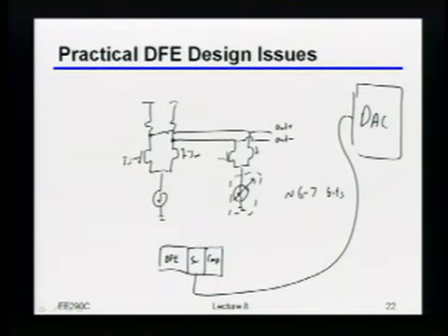Again, it's not that fundamentally the DAC has to be off on the side over there. It's just that, let's say I have another DFE nearby that I want to do. If I shove the DAC right next to the DFE itself, it'll eat into your pitch. It'll force everything to be spread apart, and then you'll be paying for really big wires in the front over there. So this kind of design, even though it looks funny, where one circuit is physically spread in like 3 different places, there's usually a pretty good reason to do something like this.